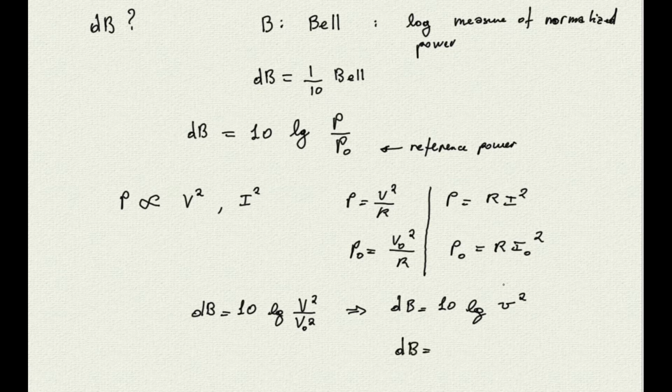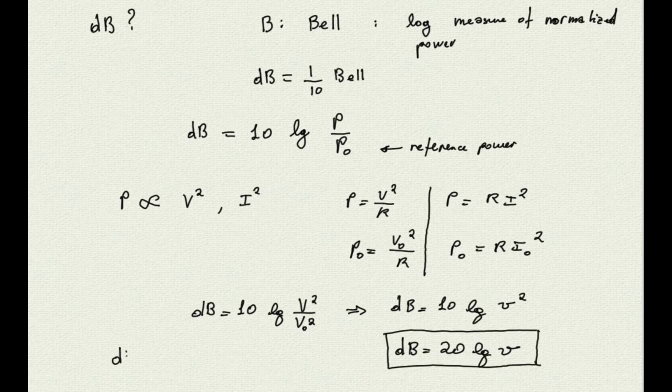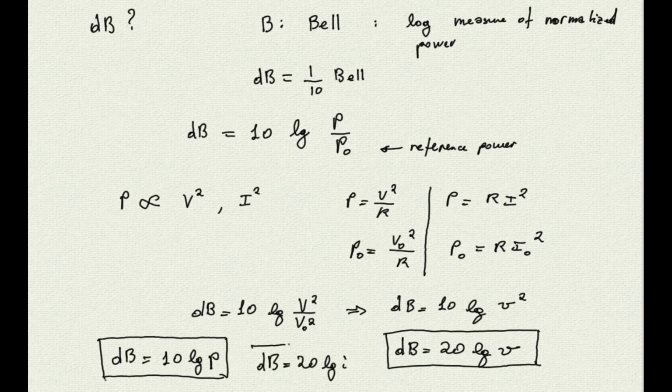If we do this right, we can always obtain the right pure number representing the magnitude of the transfer function, regardless of whether we have found it doing the calculations with the voltages, or currents, or power. And the numbers will all be consistent with each other. And that's all you really need to know about dBs.